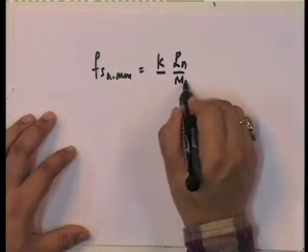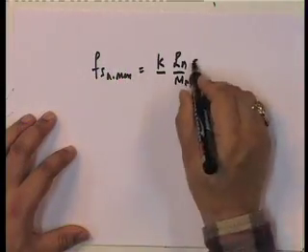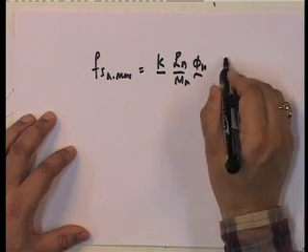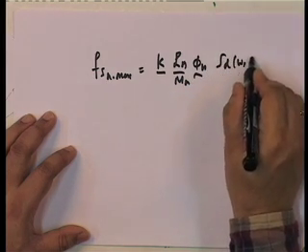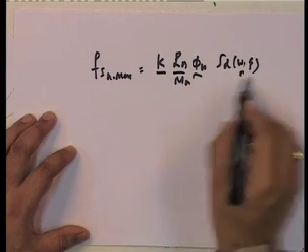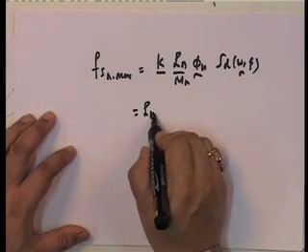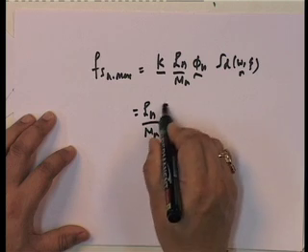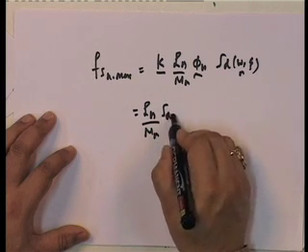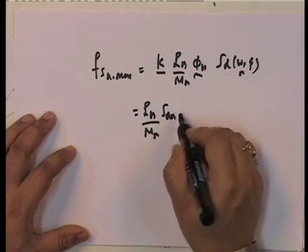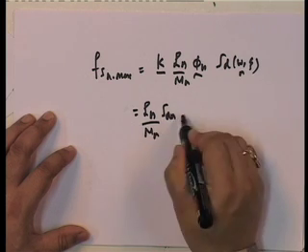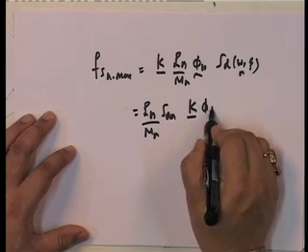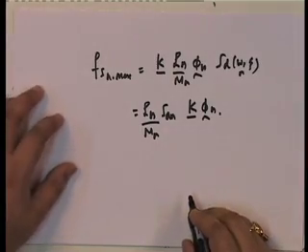Fsn max is equal to k into Ln upon Mn, which is anyway outside, phi n into Sd(omega n, xi). I can take the factors Ln upon Mn and Sdn, which I call Sdn because it is for omega n, as scalars and keep this k phi n in here.